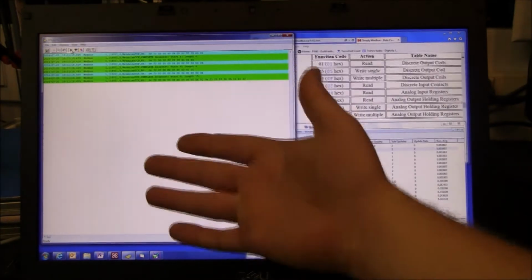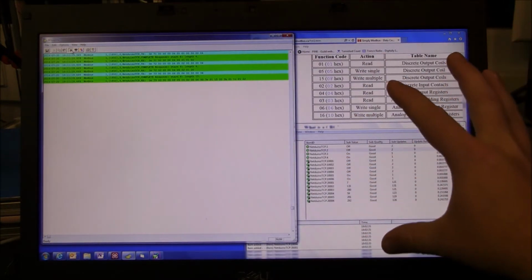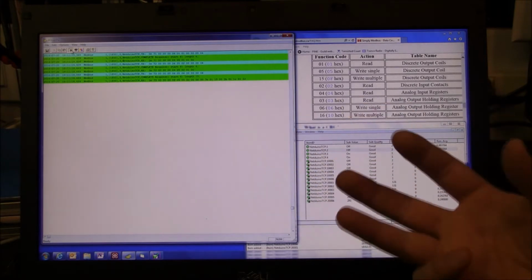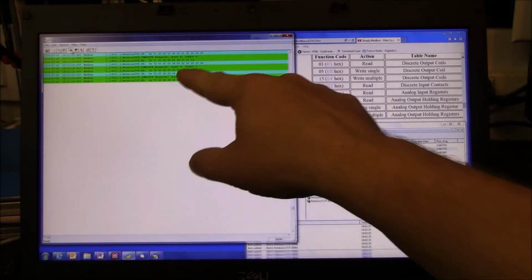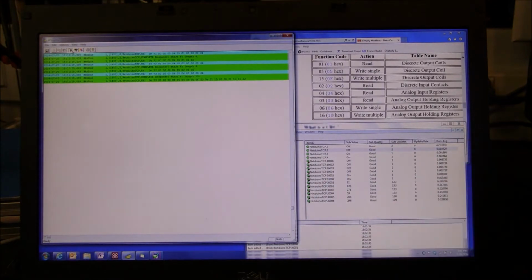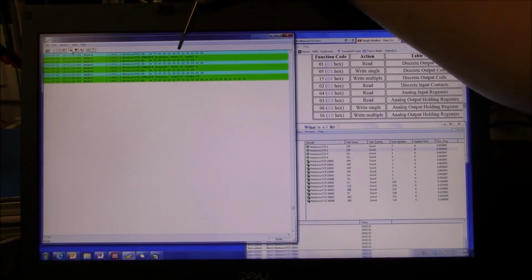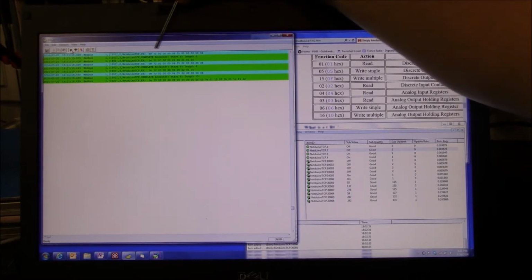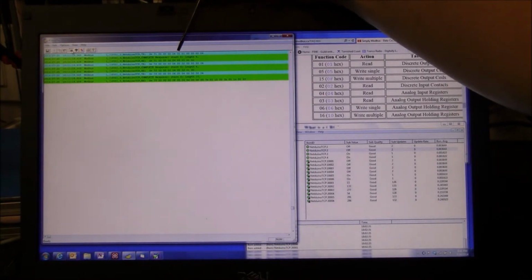So about every 5 seconds this master program on my laptop goes out and queries the slave, which is the Netduino, and there are 3 different transactions. The Netduino's address is actually 5, so you see this. I'm not really quite sure what this is in the front, some kind of checking, but anyway, 05 is the address of the device.